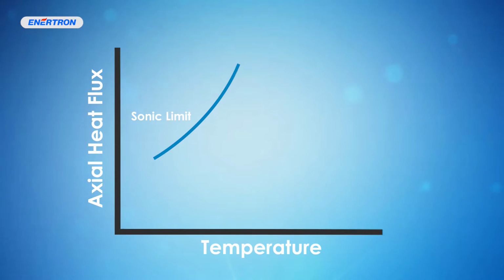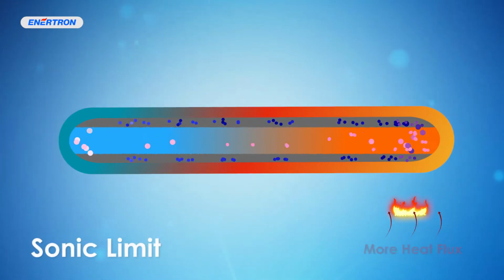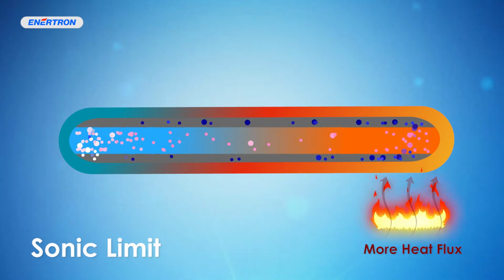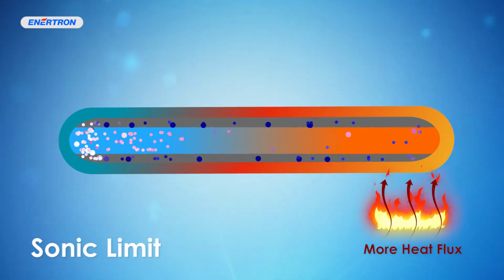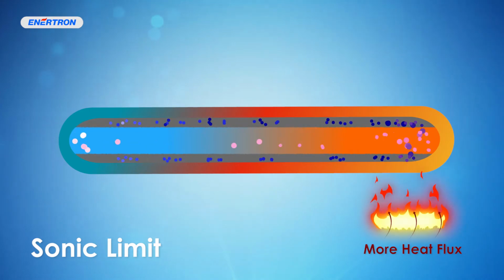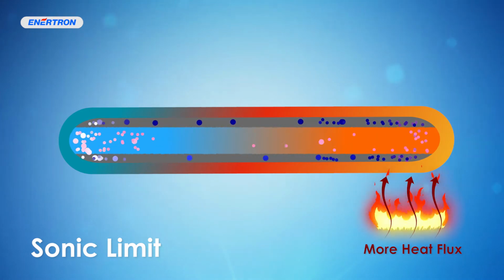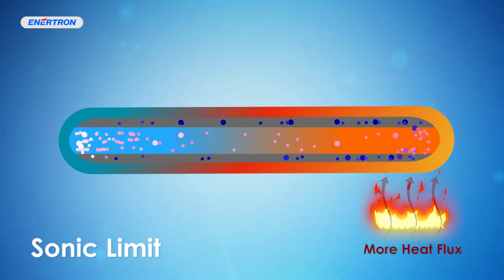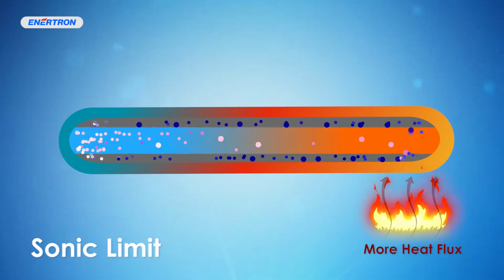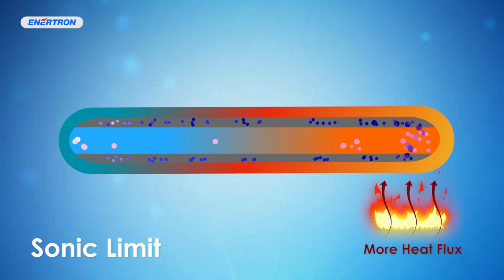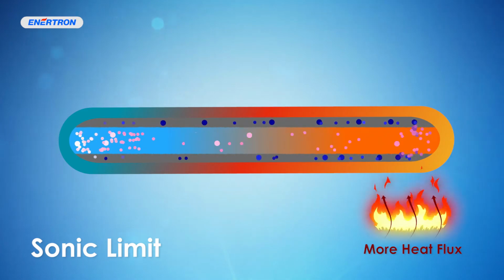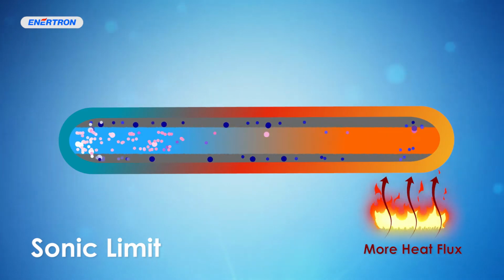When traveling through the heat pipe vessel, the vapor leaving the evaporator could reach upwards of a Mach 1 speed of sound. However, reducing the vapor passage due to flattening of the heat pipe, or creating friction due to bending of the heat pipe, or any variations in the heat input could all affect the vapor speed within the vessel. When the heat input is increasing, the vapor speed is also increased, thus building a larger pressure difference in between the evaporator. This faster moving vapor may be choked by the slower moving vapor in front.